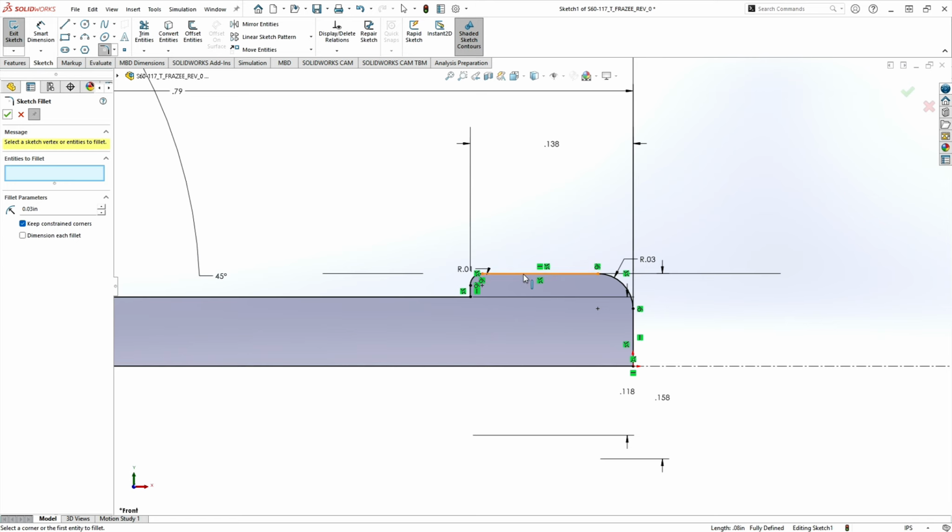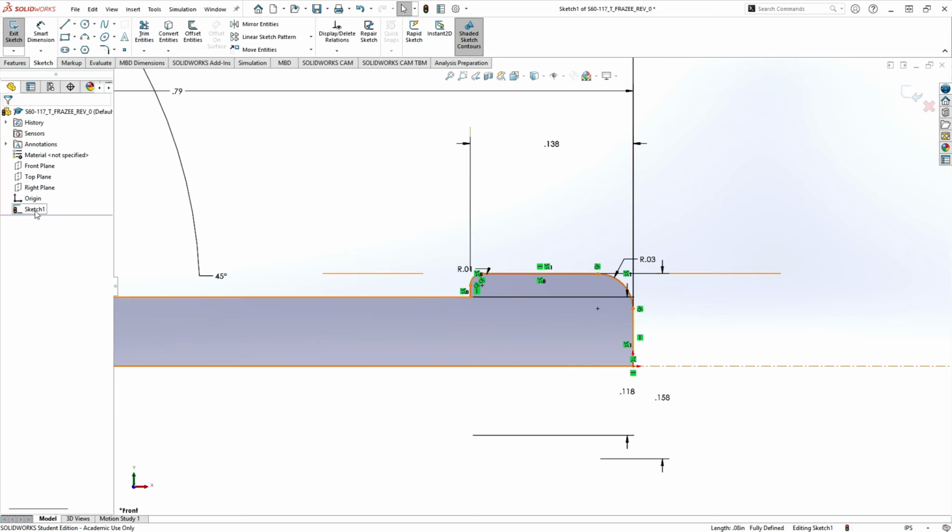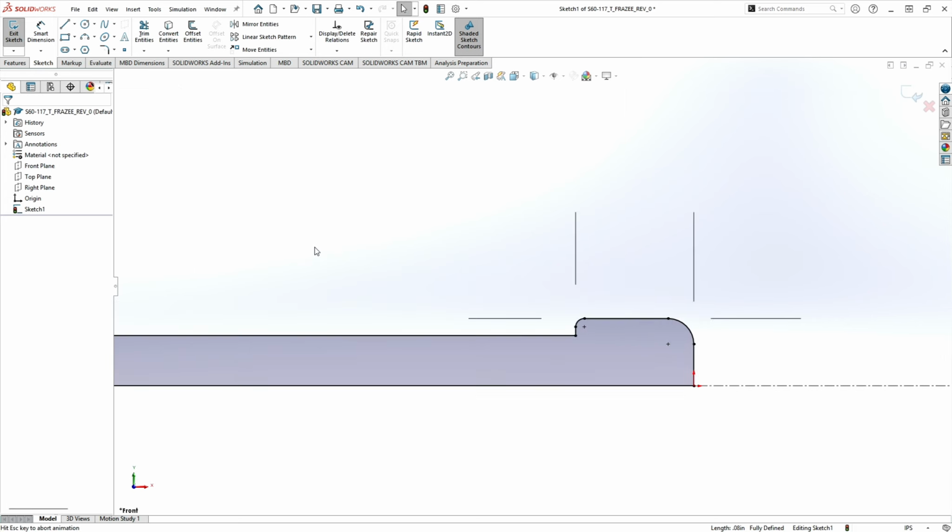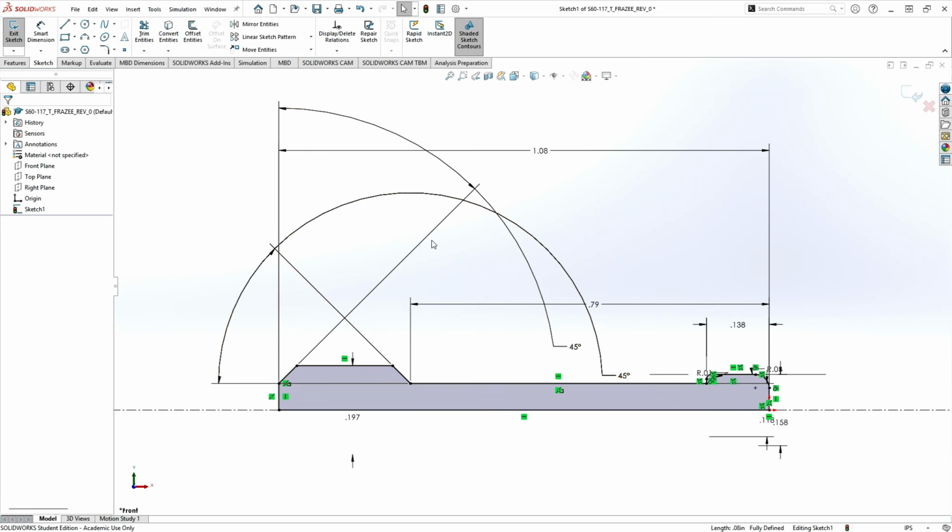For a diameter, you want the entire line to be that diameter. If you select on the endpoints, and it's not constrained right, you might get diagonal dimensions as well. So unless you really need an endpoint for something, select on the line segments for your dimensions. Alright, so we have this. This should be fully constrained now. I hit the F button on my keyboard.